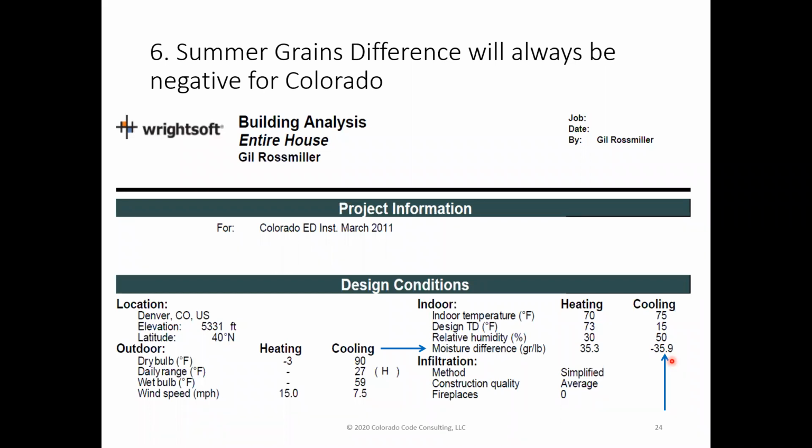So in Colorado, generally speaking, it is very dry. Yes, we just had that conversation. Very low humidity. On a design day, it's 11%, right? So if anything, we want to add moisture. That's what folks are going to want. This number here is a very big determining factor of the latent loads in the house, right?